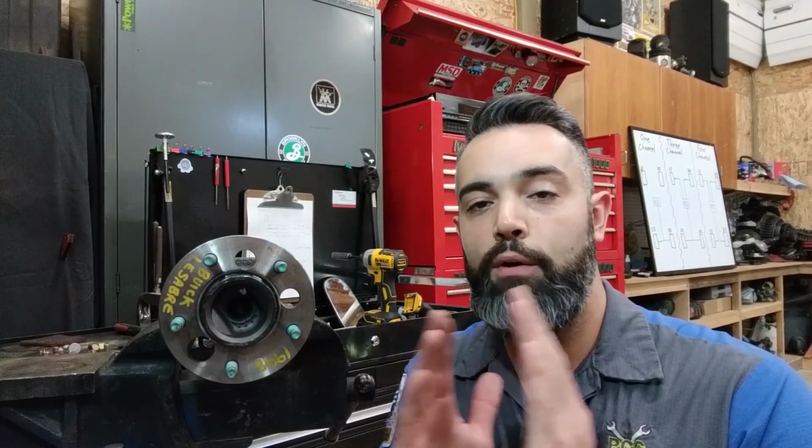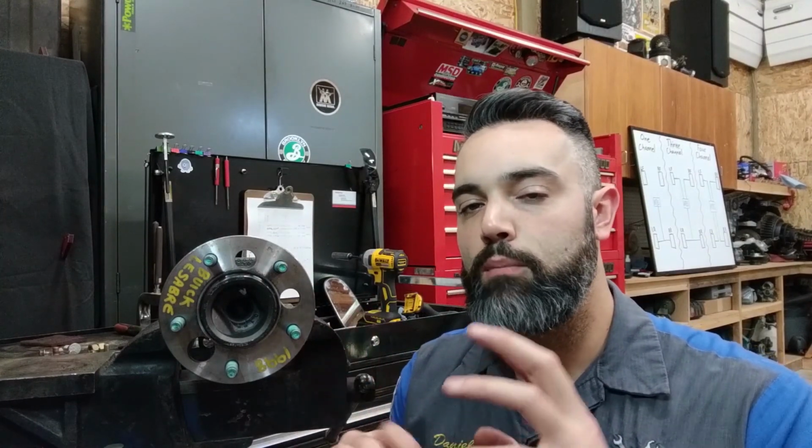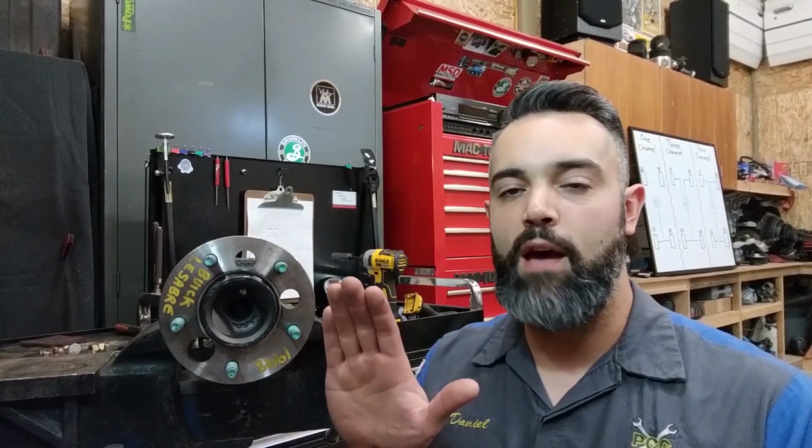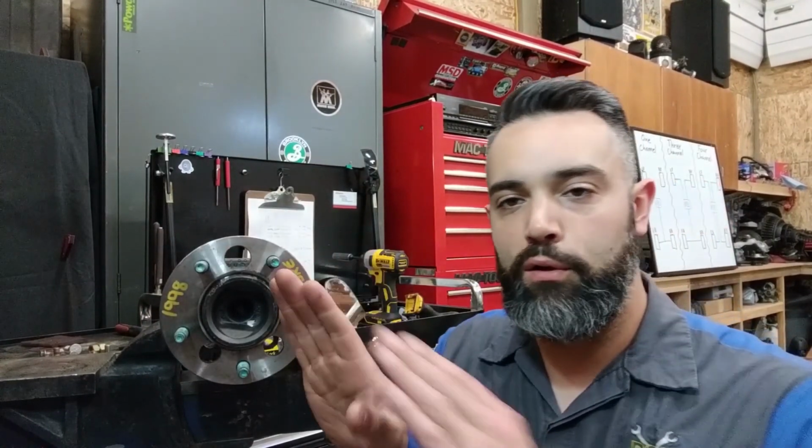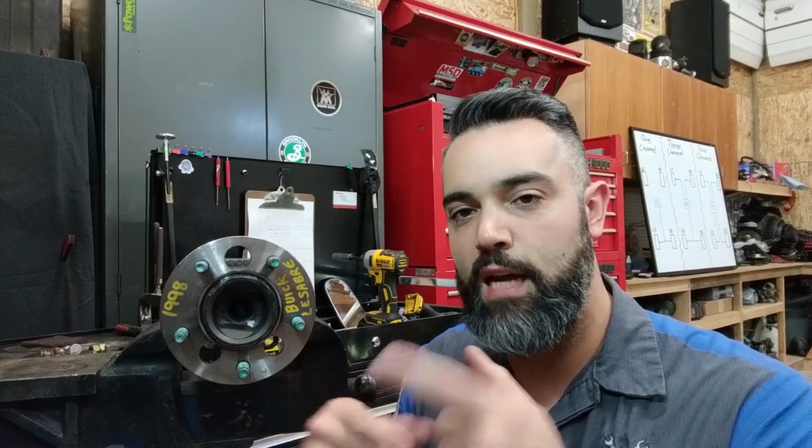So how is it controlling this? Well, it's using brake pressure for one. What it's doing is routing the fluid through a series of valves that are going to open and close, block fluid from going into the brakes. Meanwhile, the driver has their foot on the brakes, so there's an input signal from the driver applying the brakes, and that fluid is going to the wheel that is going to lock up. Normal function of the brakes. Once it detects a slip, it's going to close off the input from the driver, and then it's going to take over control of the hydraulics on the system. This is done through the hydraulic control unit.